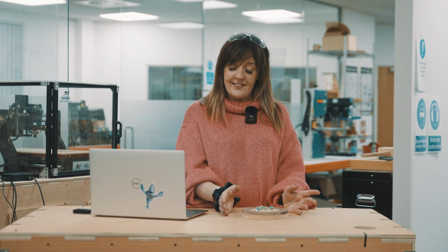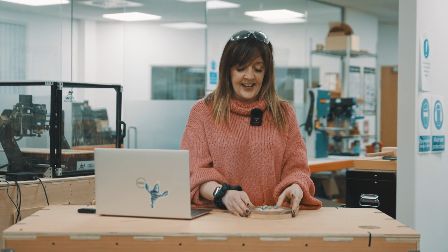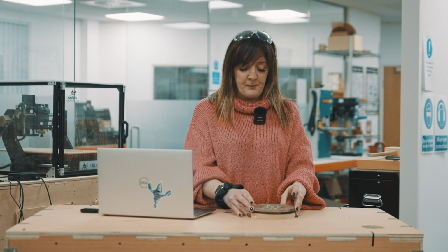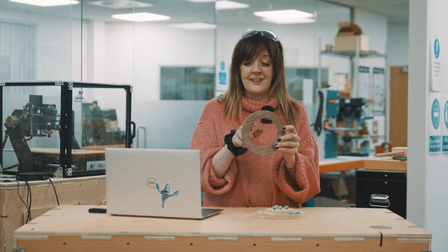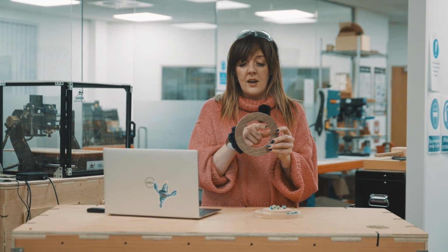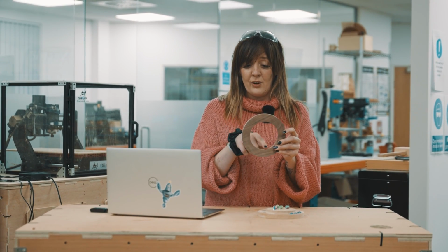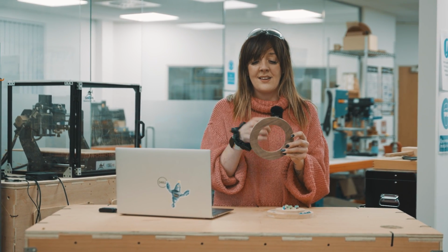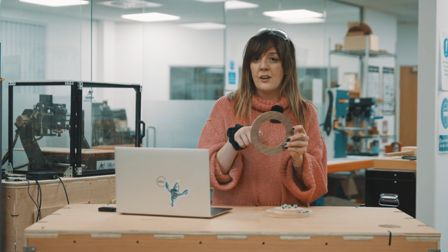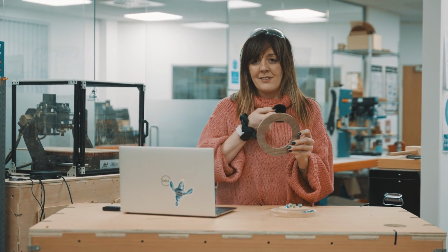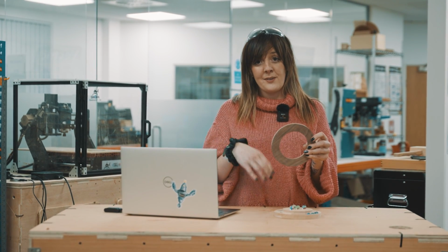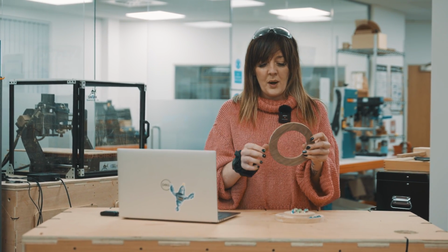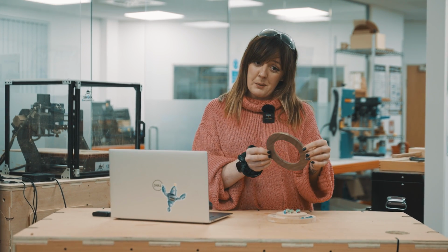I really like how this has turned out. Love the contrast there. I think it's really nice. One thing that I would change is, rather than do a profile pass for the inside where I had to detab the waste material, I'd actually just do it as a pocket pass. That way you're clearing up the edge, you're going to get a nice smooth edge without having to sand off all of those tabs. So I'm going to change that for you in the file, so the file you'll get is going to be the perfect one. And that's pretty much it.